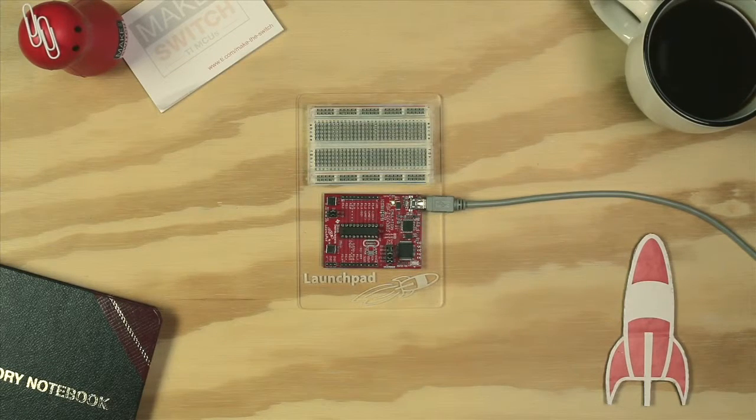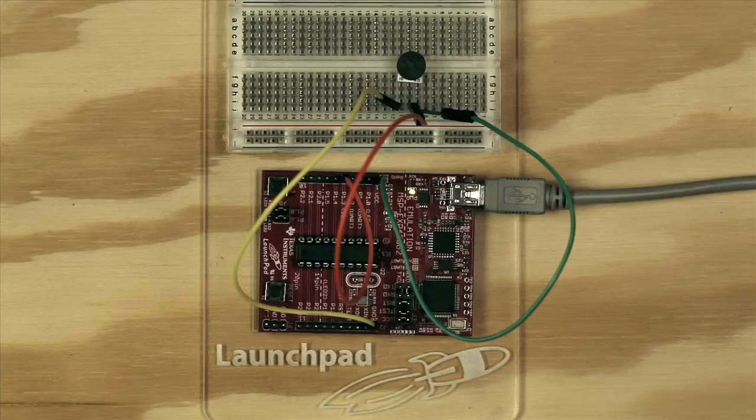Today we are going to show you how to obtain output data from the MSP430 LaunchPad and display it on your personal computer using Energia. In this example, we will be using an analog input like a potentiometer and display its digital value after conversion by the MSP430 on your personal computer. We will be using serial communication between the LaunchPad and your PC to send the results for display.